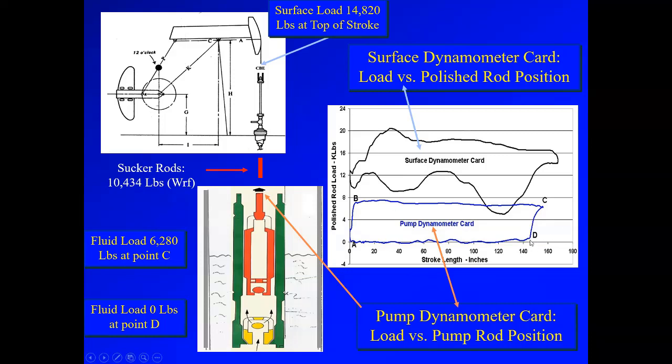There are factors that affect the pump card shape, and hopefully we are accounting for most of those, and there is not much residual friction or other things affecting the pump card shape. So most of the time we have a decent dyno card shape available, and with Echometer equipment it is more reliable because we have much higher sampling speeds than conventional controllers. So we have more details in a pump card coming from an Echometer dynamometer sensor. We will be focusing on interpreting the dyno card shape at the pump.